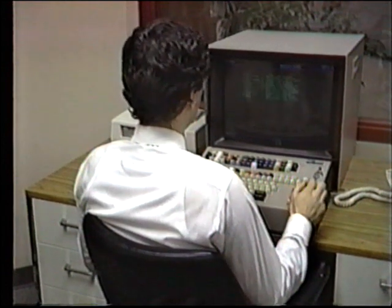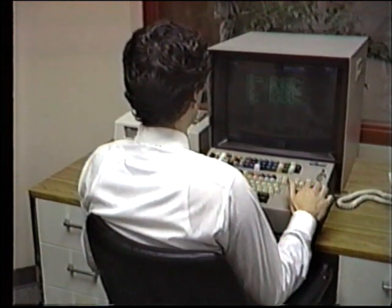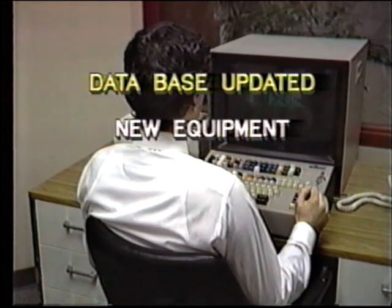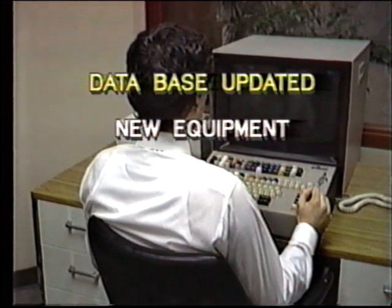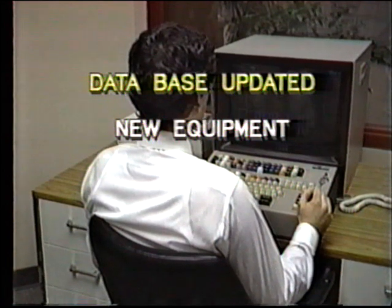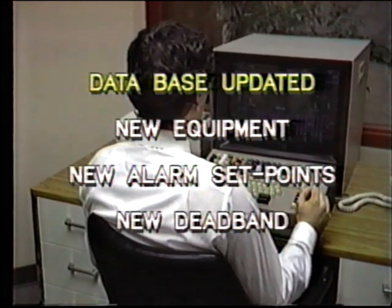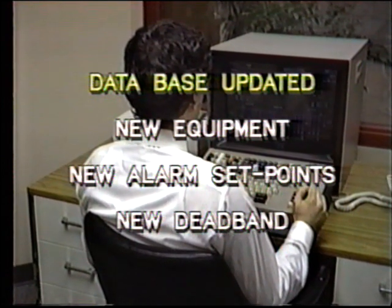One example would be the database which resides in the memory. This must be updated as new equipment is installed or ratings are changed on existing equipment. Another case would be modification of alarm set points or the deadband for exception reporting.